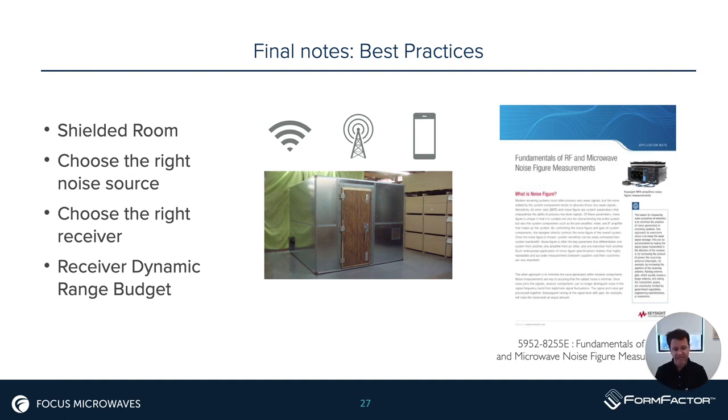You might need to recalibrate sometimes if you want to hit different frequency points. As the noise source is calibrated at given fixed gigahertz points, you might want to have some points in between so that you don't have to interpolate. You could basically get that pre-calibrated. So they go into that in quite some detail.